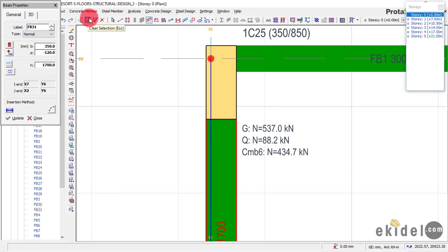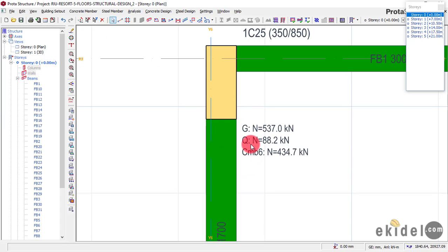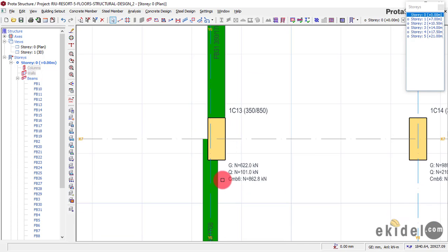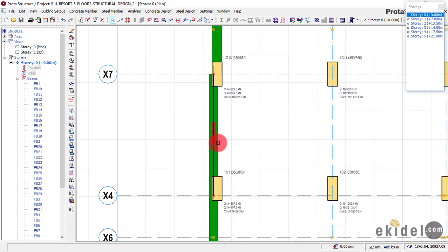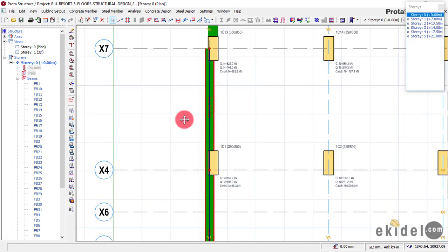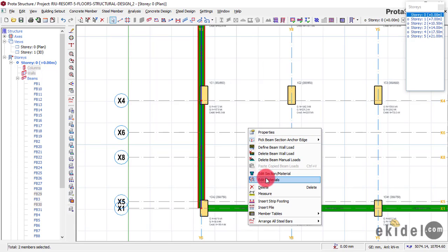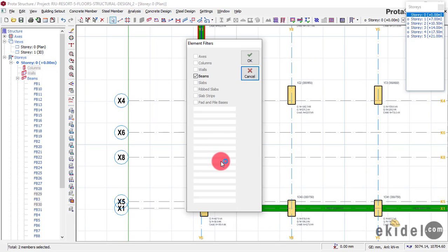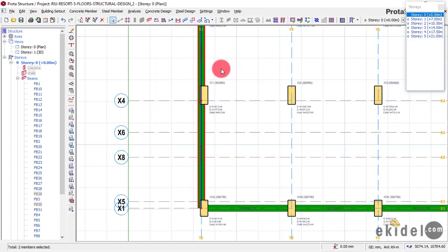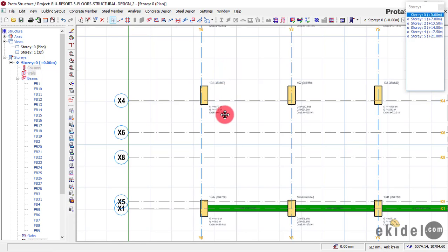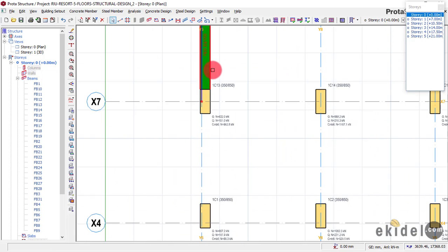So right now, I'll click on escape and then go back and change all the beams on this line to have the same properties with this. Okay, so right now, I'll go over here and remove these other beams, and then make sure they flush. So whenever you're performing a raft foundation design, you must make sure you put everything into consideration. As you can see, I have put into consideration the column to beam eccentricity, and I make sure that the column and beam are all flushing.